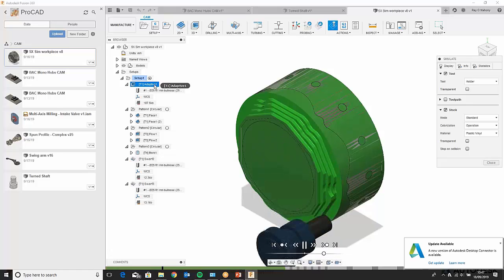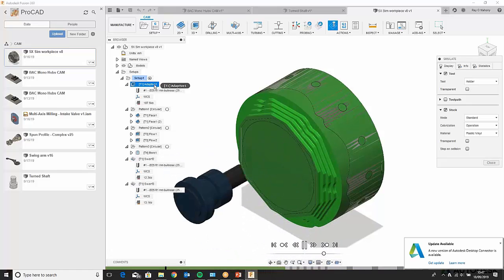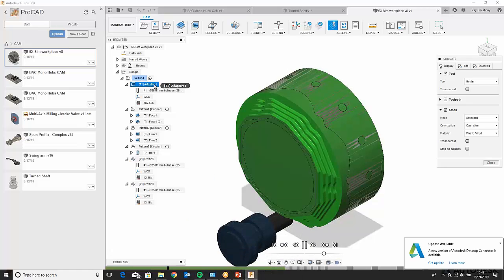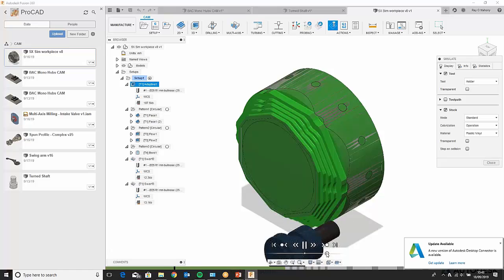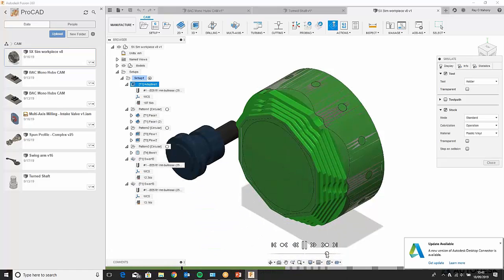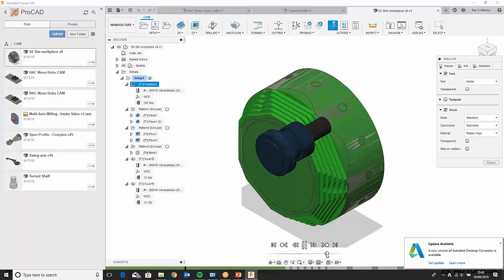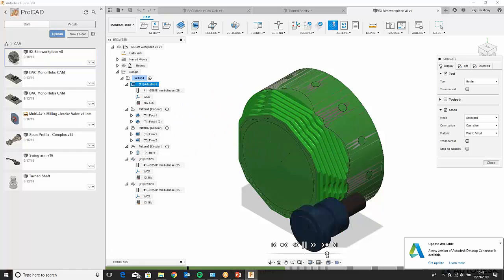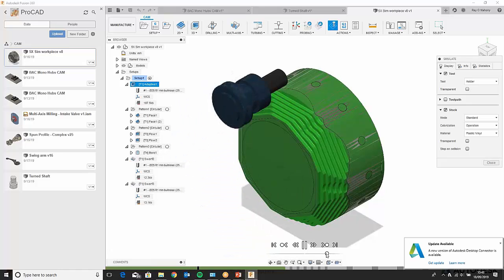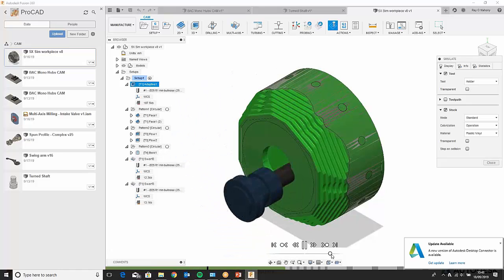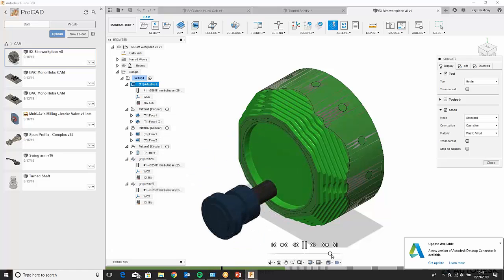So we're removing a lot of the heavy material. This is our roughing phase. And then what we can do is speed this up a small bit. So we're just moving along and getting into the parts that we need to be concerned with. And now we're going to start moving on to the next machining process. So again, you can see the roughing is pretty quick. Let's go. And now we're going to the internal bore.